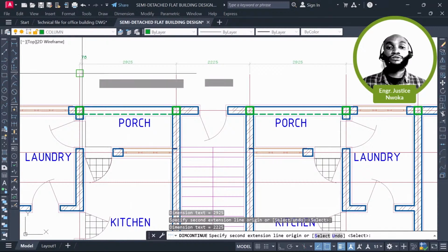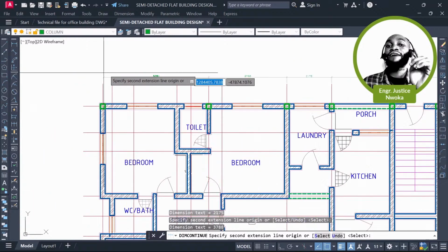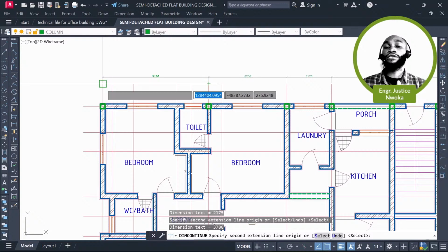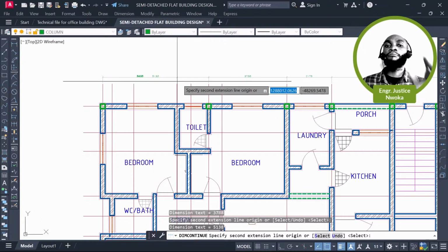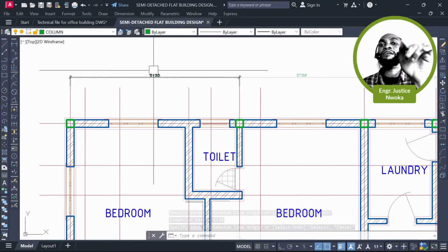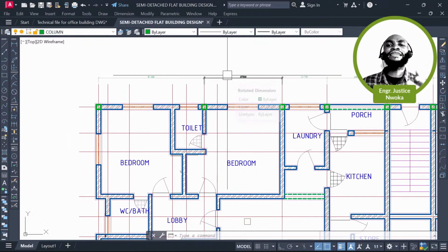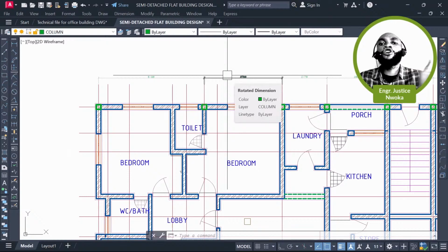Now most people see this as very stressful, but if you want to have issues in your design, don't do your GA. Most people think that performing their GA is a waste of time, but that is the most critical part of the design of your structure, because that is when you are planning the stability of that structure by placing your columns and beams. So you must spend time doing your structural frame.